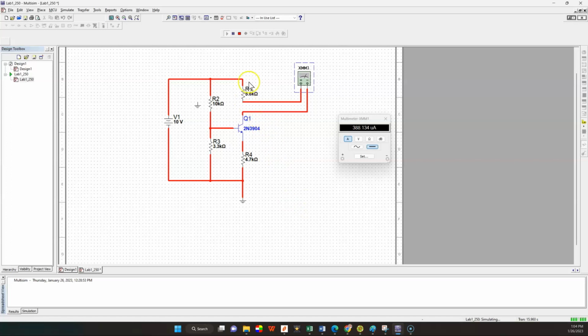What else? You need to measure the current in the base. So how you do that? You disconnect your DMM, because remember, you have only one DMM in the lab. And then you want to measure the current in the base here. So what should you do? Disconnect this wire. And the current will be going from this point towards here. So the positive should be connected here to the midpoint of the voltage divider, and the negative to the base. Don't forget, you got to connect the circuit that you separated before, or you will get zero. And adjust it to amp, DC, and then turn on your circuit to measure the current at the base.